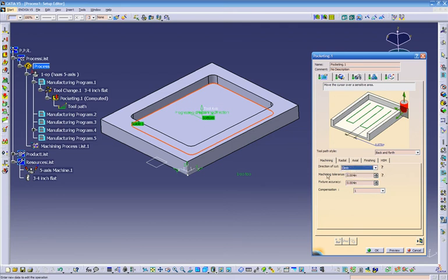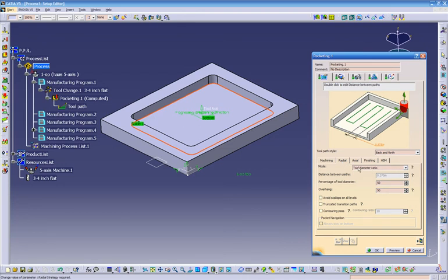I never change it. Over here is the tolerance. You can see over there. Radial is asking us over here the tool diameter. So you just put over here kind of like a step over. So right now it's 50%. So the step over ratio is 50%. Or we can put to distance. So right now we'll put step over 375. Step over from here to here, we get 375. Or we can put the step over ratio or maximum distance.